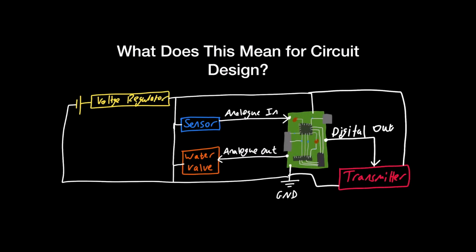The next step is to consider a circuit block diagram. We need the power source to connect to all components to provide power. All power needs to be connected to ground to complete the circuit and prevent shorting. Some kind of voltage regulation needs to ensure that external factors such as temperature don't affect the power provided, so certainty is needed around powering the system. We may need different voltage levels at a later point depending on the exact devices that are chosen.